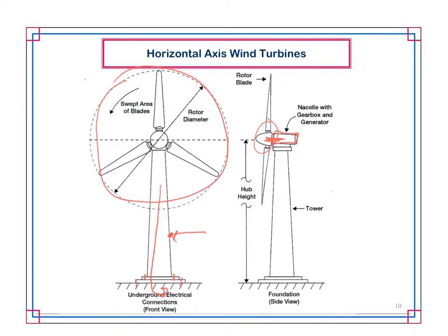Other applications that I've seen, what they do is they heat them up. In really big turbine applications, they actually have something called bolt heaters, where they put a heater directly in the center of the bolt, and they heat the bolt up, and its expansion and contraction is different than the nut. And so then you can take the nut off. Otherwise, if you just did it with a wrench or whatever, even if you had miles of pipe wrench, you wouldn't get it off. You would probably snap the bolt or whatever. So it's a real process in getting those erected. Really fascinating if you can ever get to see it.